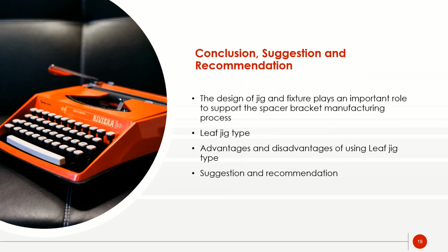However, the disadvantages are, with multiple holes required to drill, chips may accumulate inside and cause trouble to the operation. Also, play in the hinge may affect the drilling accuracy of the hole if the drill bushing is fitted in the leaf.